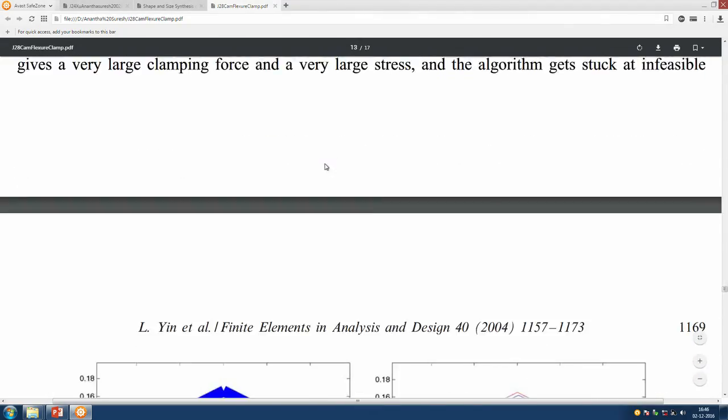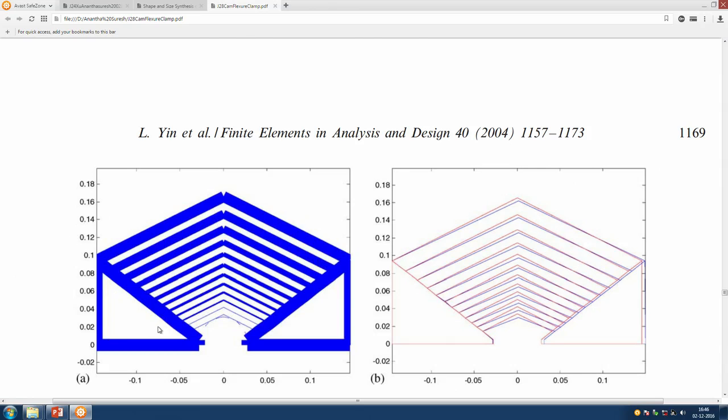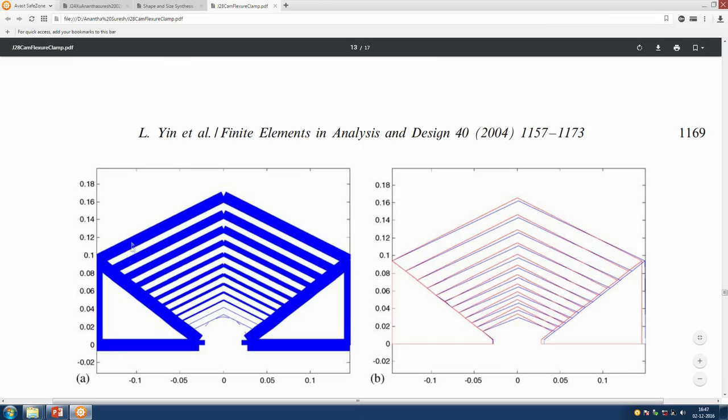When we did that, something interesting happened. So, we showed that when you have the elliptical hole here, when you take a beam like this, okay, from here to here, a single beam, no matter what width it is, it does not serve the original requirements that they have, right. So, we thought, okay, how about using the stress, each one of them has a particular width here, that is the size optimization, and the height of this, compared to the span of this, how high it can be, they are all different here, even the span is changing. So, there is a notion of shape change here. Topology, we believe that it was suggested by topology optimization. In fact, it was, because we tried intuitive a lot of them, we did not get anywhere.